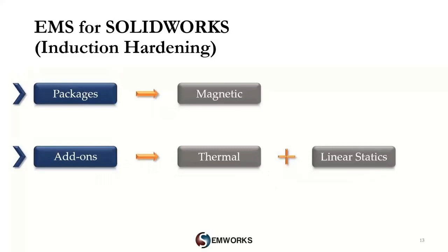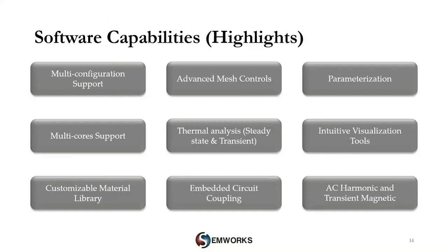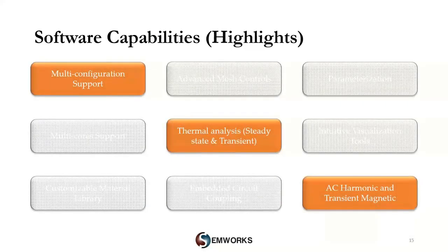To simulate an induction hardening problem using EMS software, magnetic package with thermal and linear statics add-ons should be used. Now this slide represents a small subset of capabilities available in our EMS software product. To simulate an induction heating problem, 3 capabilities are highlighted and utilized in the product demo you saw earlier. Number 1, multi-configuration support. This capability of SolidWorks enables users to maintain multiple versions of a part or an assembly in a single file. The differences between configurations are established by changing dimension values, suppressing features, and changing other parameters.